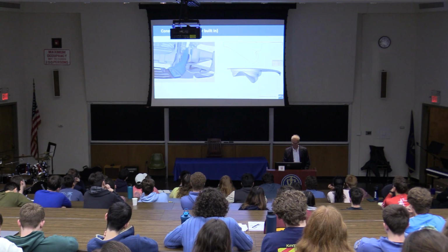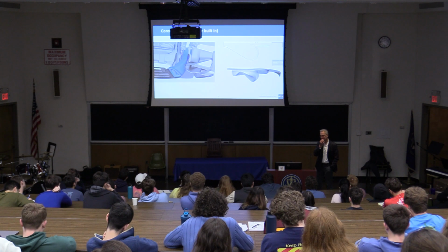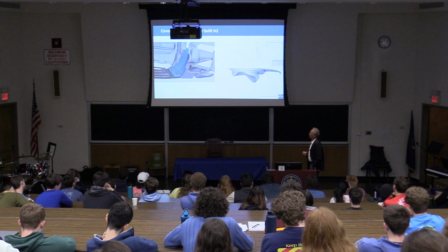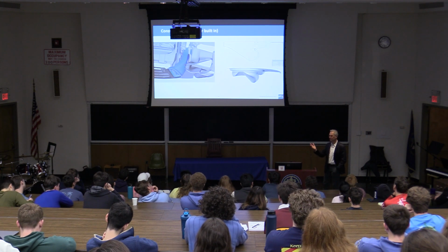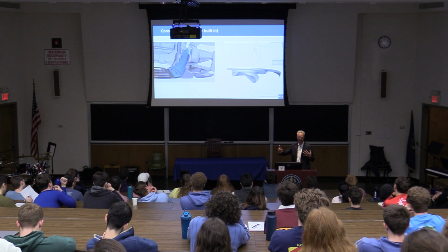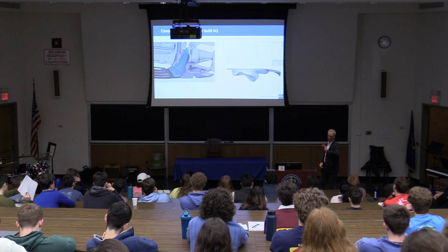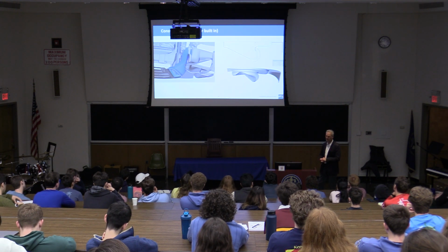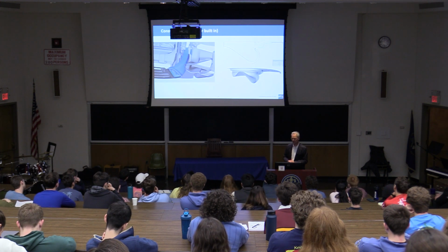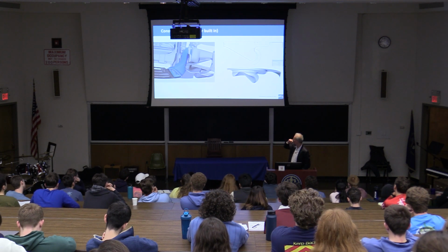Constraints. I already said, okay, a typical constraint is that, for instance, you might have to have a certain displacement for your hull, or you want to have a certain center of buoyancy, or the center of buoyancy has to be between this and that. That would be inequality constraint. If it's fixed, it's an equality constraint. If you say, okay, it's 1,000 tons and nothing more and nothing less, then okay, it's an equality constraint. Often things are inequality constraints, luckily, and you have to sort of say, look into them.